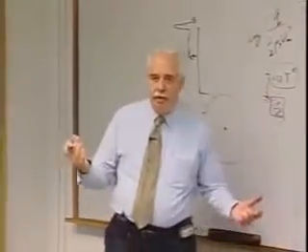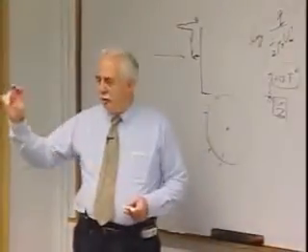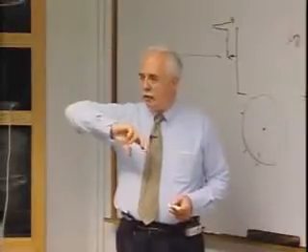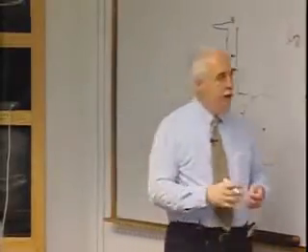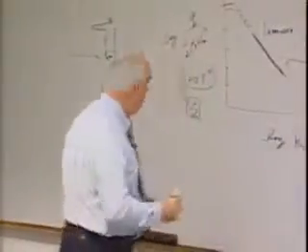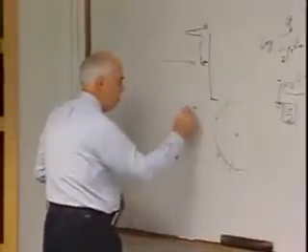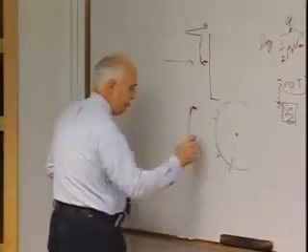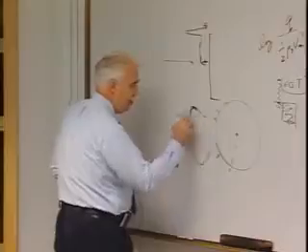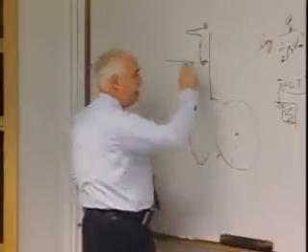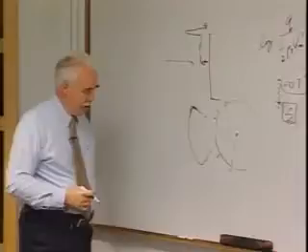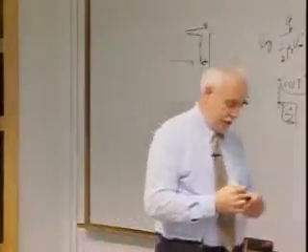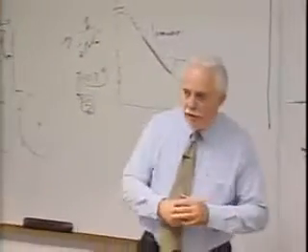That's very efficient. I can design my thermal protection system to be so thick, and I manufacture it, produce it over the entire surface exactly the same. That's wonderful, except I still have the corner problem, and so I round the corners a bit. This is only from an aerothermodynamic standpoint now, and so I don't have this corner edge heating problem nearly as much. Well, that's fine, except a zero L/D vehicle gets kind of high G's coming in,